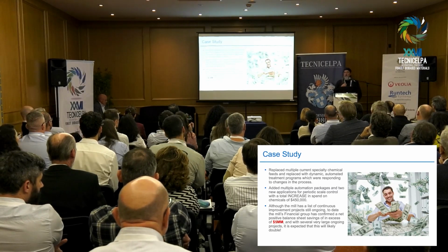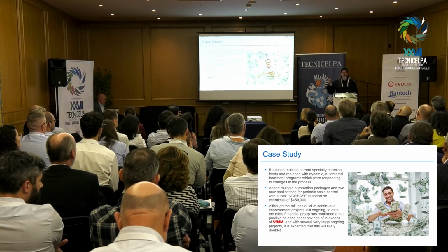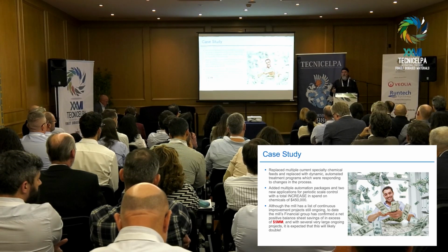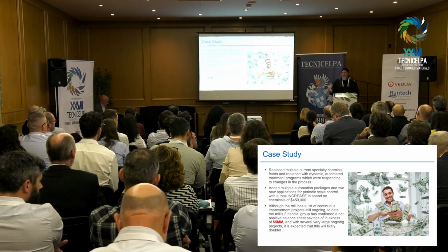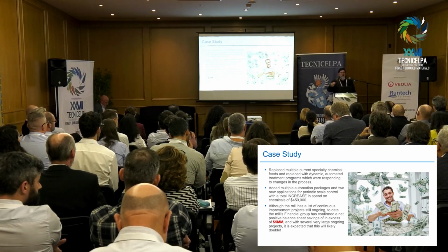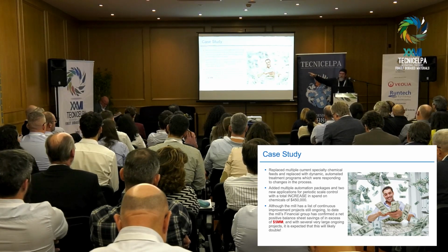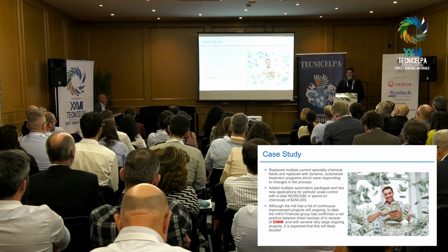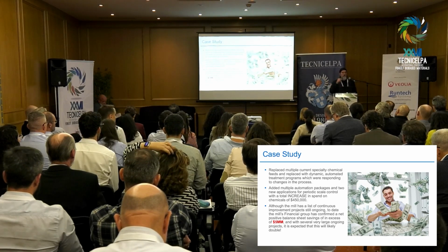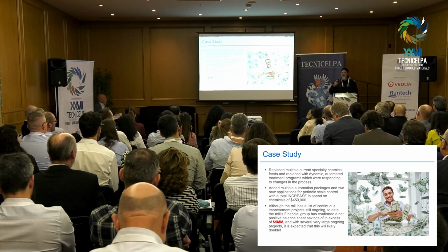Then we had to come back as a chemical supplier. Our chemistry had to be automated because what they needed for defoamer on high kappa softwood, and suddenly I'm going to cold pulp bleach, it's totally different. So how does the specialty chemicals react, and how can I use those to help stabilize the transitions? When it all got said and done, we added $450,000 of specialty chemical cost because we want to make sure we're putting the stuff in where it belongs. We had some chemistries only on some grades to optimize the chemistry, the reactivity.